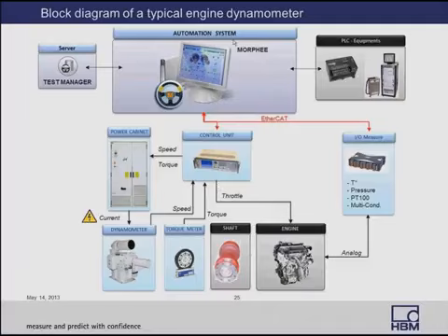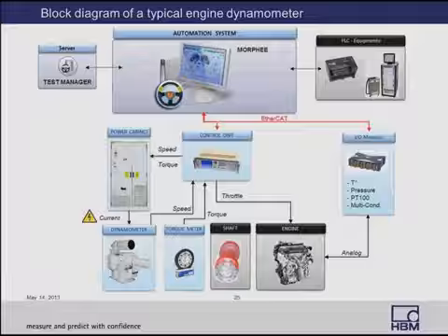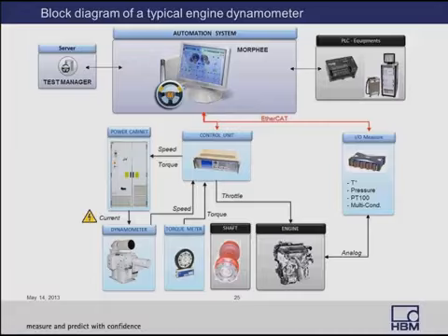So Morphy can mainly do two things in the engine dynamometer application. Morphy can read information first, so that's why it's the data acquisition software, through the EtherCAT bus in real time up to 10 kilohertz. We're going to be able to read temperature, pressure, different analog signals, but also control analog signals and control digital outputs.